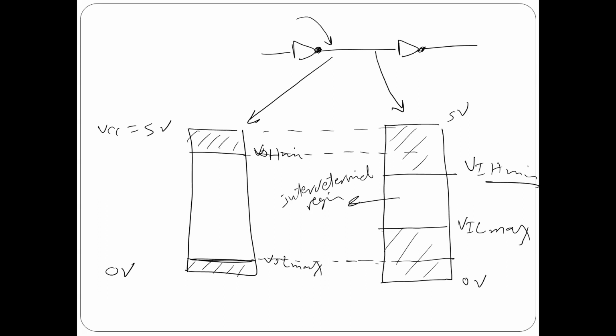This is the purpose of the lab. In the lab, try to change the input and see what's going to happen when it comes to this region. What's going to happen? Again, if you want to use it like a logic circuit, it should not be here because it can make errors. It's not going to work as a logic circuit. The transistor is not going to be totally open or totally closed. So it has to be either here or here.